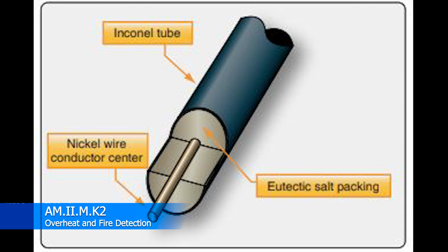You can also wire these so that if there's a break in the middle of the Fenwal system, the section where the break has happened is the only thing that's really affected. The two ends will still continue to detect the fire, and will still work in much the same way, which is pretty awesome when you think about just the redundancy of that.